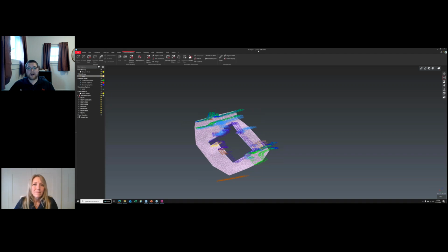Where's the sidewalk? Where's the walls, the buildings, things like that, center of the road, curbs, drainage, things of those nature. So if you take the time to get all that ahead of time, it's kind of like a domino effect. The whole process, even in the field, if you're doing a couple extra scans to make sure you pick up everything well, makes registration quicker, it makes your data extraction quicker, and it makes you get that end deliverable even quicker. So as long as they don't cut a corner to save an hour in the field, you're going to save a lot more hours as you move through this whole process.